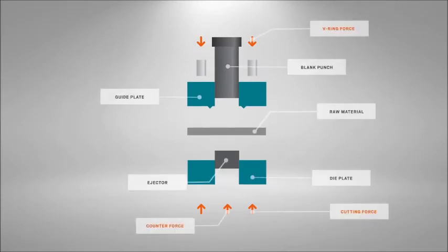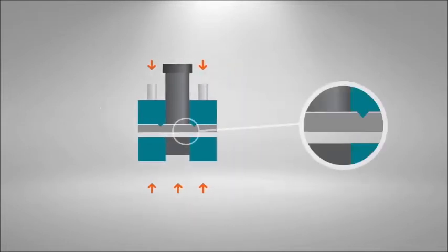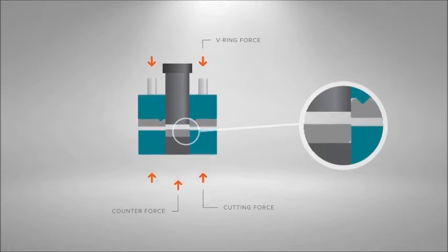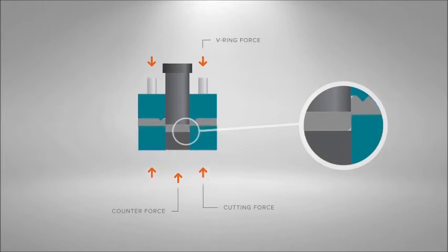Fine blanking is when there is no fracture zone in the cutting process. This allows the blanking to hold very tight tolerances. It maintains flatness and enhances the sheared edge, eliminating die break or edge fracture.